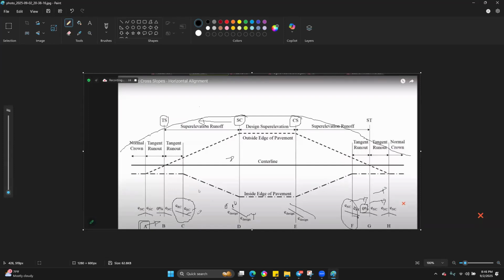For instance, let's say this is -2.5%, this one should be +2.5%. Like it's basically the normal crossfall, but now in the opposite. Yeah, I hope you get that. So you find that if the distance for you to move from -2.5% or whatever normal camber you have to 0%, then from 0% to the same normal camber in the positive direction should be the same.